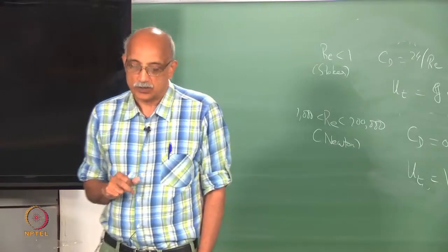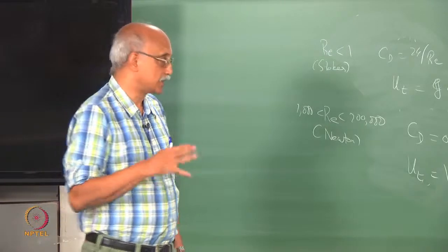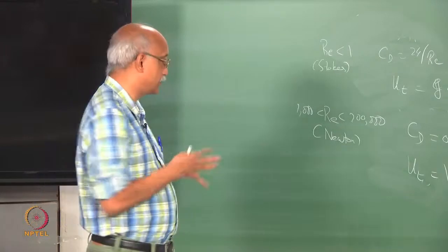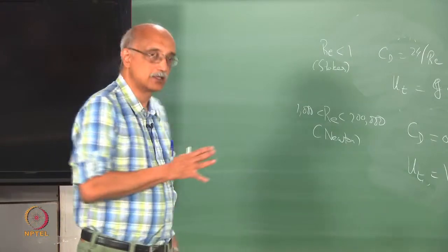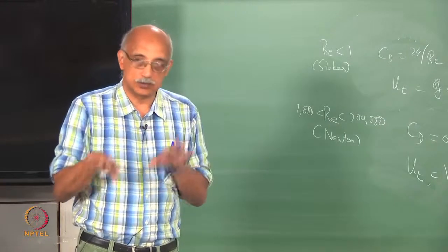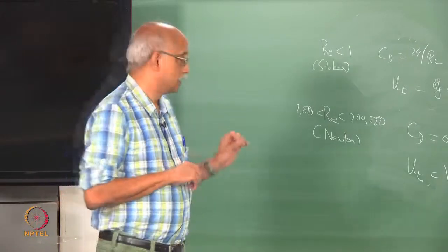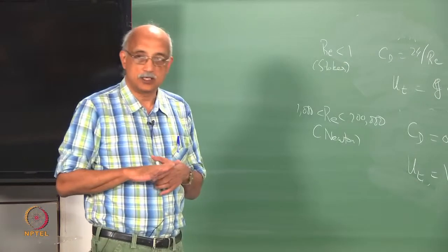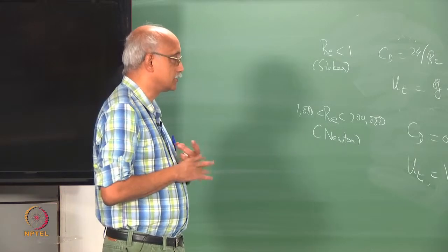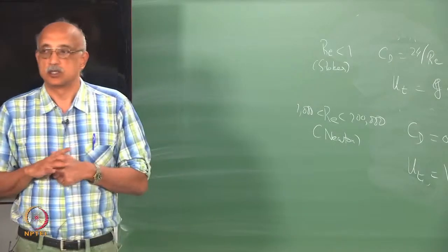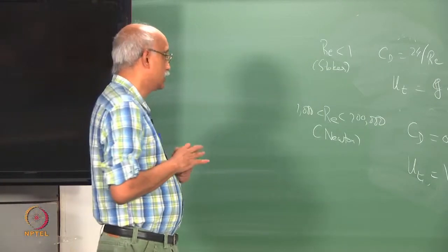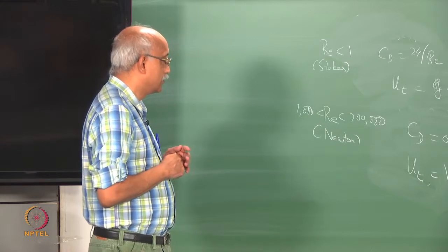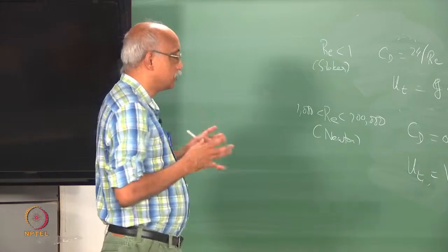diameter is concerned. So, here again you have to think about all this from a process engineer's viewpoint. As your Reynolds number changes, you have to realize that some of these dependencies are going to change. So, either you try and control the Reynolds number, which is one of the most critical flow parameters, or you try to allow the Reynolds number to vary, but then realize that some of these qualitative or parametric dependencies are going to change as the Reynolds number changes, and therefore you design accordingly.